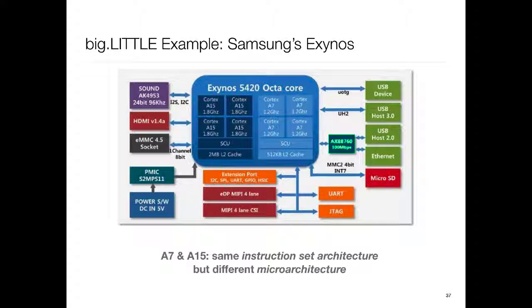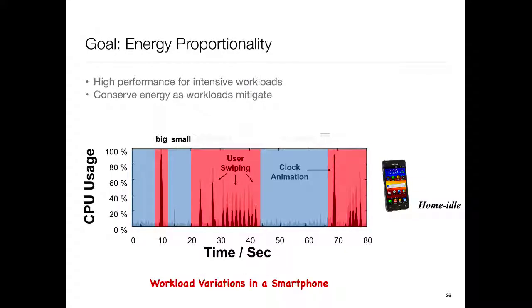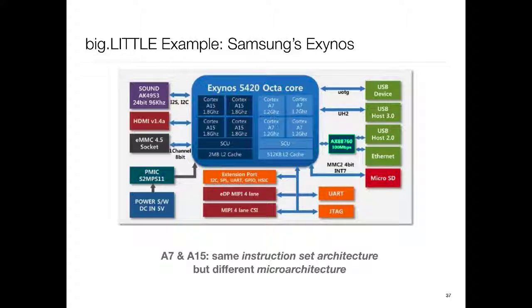So this is pretty complicated under-the-hood control, but if you get it right, there are a lot of benefits to be had. In this Samsung design, what you would see here is 4 big A15 processors and 4 smaller A7 processors, and then one switches back and forth. And there are additional constraints: within each pair, you can have only one processor up. So you have to make a choice of big or little. You can't have both up. Anyway, that's the concept.